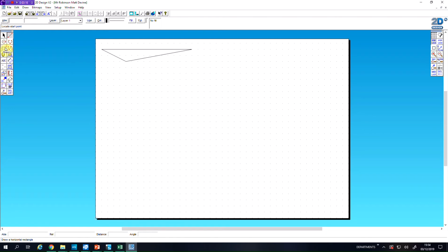The first thing that you're going to do is to check the size of it. So we're going to check the width first of all. We're going to go down to dimension lines here, click and hold, and out pops draw horizontal dimensioning. So remember, we are going to click at this side, click, click, boom, it's 150. We're going to do the vertical, we're going to do click, click, boom.